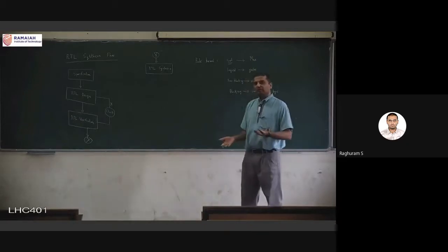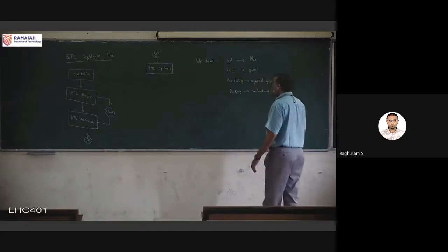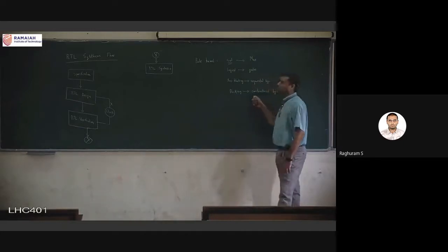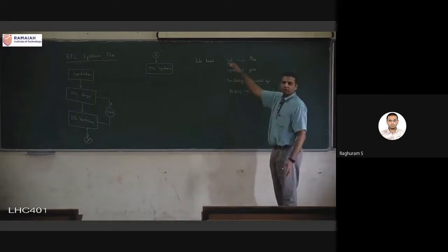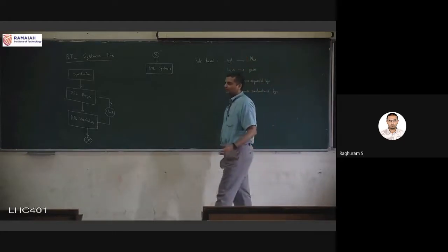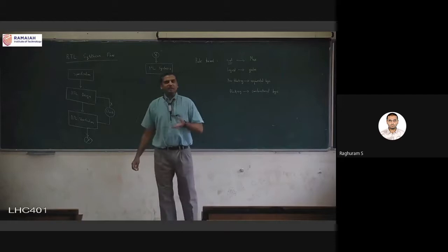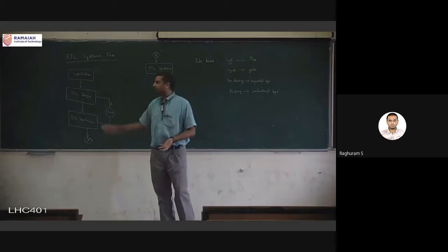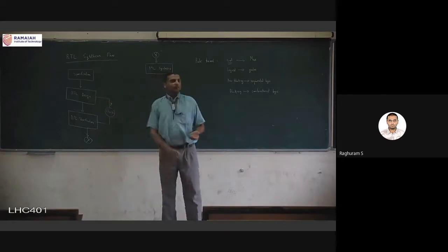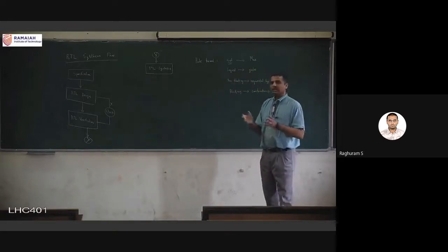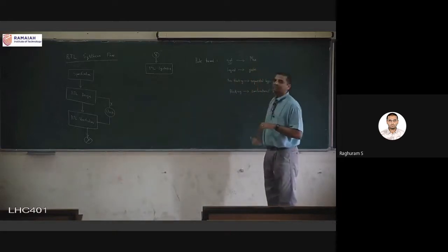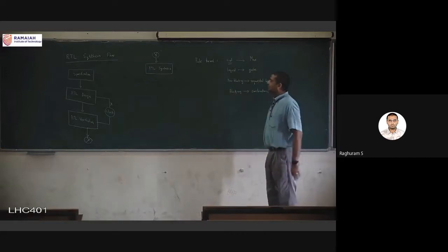When you're having blocking statements, that generally means that you are designing combinational logic. So this is a large set of rules. Okay, so based on these rules, whenever some statement comes in the Verilog code, in the RTL code, you can directly translate that into a gate level description using these tools. So that is the main thing in RTL synthesis.